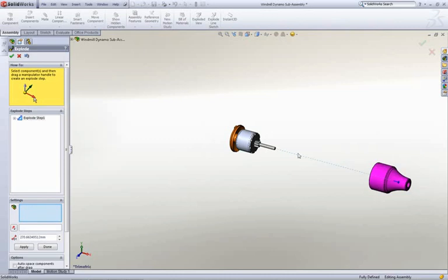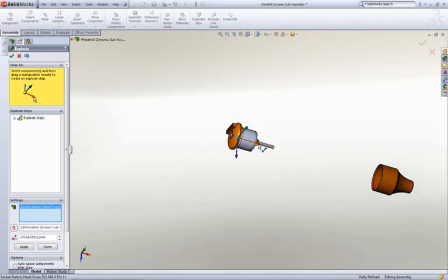Next, remove the parts from the top of the assembly until only the rotor subassembly is left. Select the bolt, click the X-axis, and drag it away from the assembly. Now, move the dome away from the assembly. There is one more component to remove. Select it, click the X-axis, and drag it away.